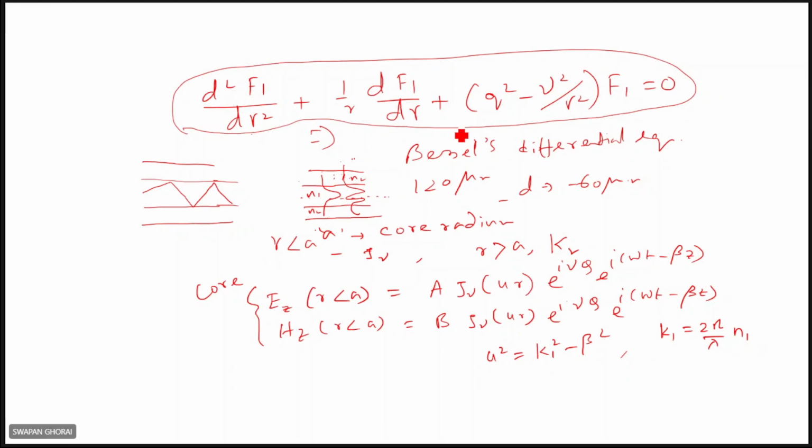In this context, you should keep in mind, here we have considered the fiber. For a single mode fiber the core is generally 2 to 10 microns, as we have seen, and the cladding must be a minimum of 125 or 120 microns, 60 microns radius minimum. So this is 125 microns, but theoretically this cladding can be infinite,